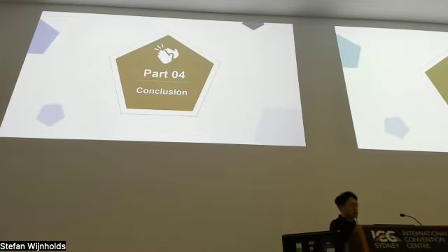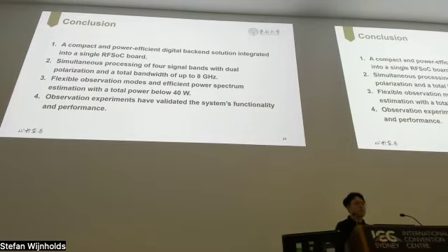And the last part is the conclusion. So we designed a compact and power-efficient digital backend solution integrated into a single FPGA SoC board, and we can do simultaneous processing of 4 signal bands with dual polarization and a total bandwidth of up to 8 gigahertz. And we offer flexible observation modes and efficient power spectrum estimation with a total power below 40 watts. And the observation experiments have validated the system's functionality and performance.